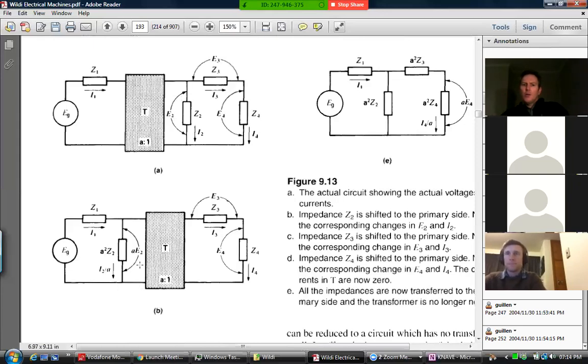So in the equivalent circuits analysis, we must bear in mind that if we came along with a voltmeter and tried to probe across here to see what voltage the voltmeter would measure there, in theory, it would measure A times higher than what it would have measured if you'd put the same voltmeter across here. Okay, quite a key principle this.